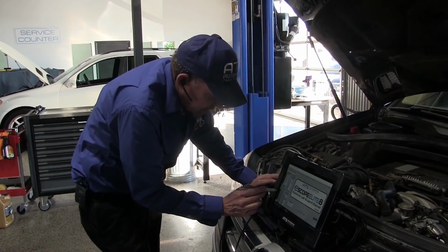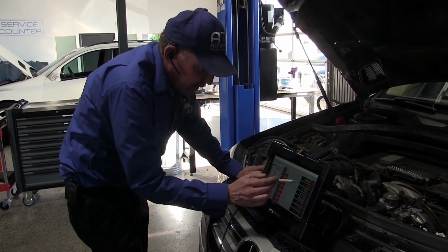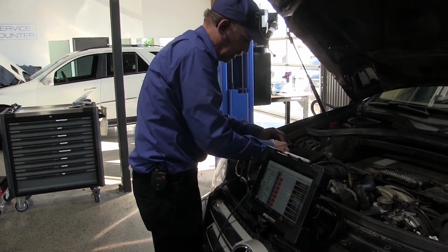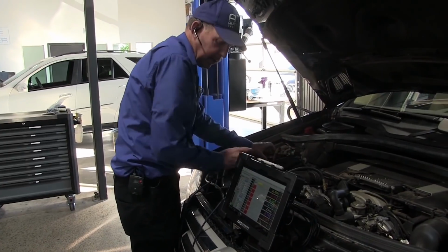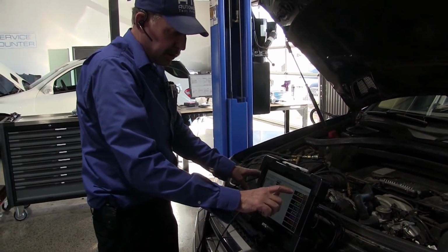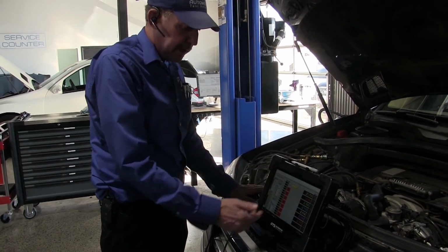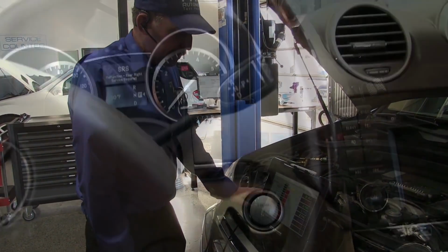So we're going to pick the transducer, and then we're going to zero it, and then we're going to come over, and we're at 0. I didn't plug it in yet because I don't want fuel pressure on here before I zero it. So now we're going to plug this onto the rail. It's not running yet, and we have 21 psi. So now what I want to do is let's go ahead and start this vehicle up.